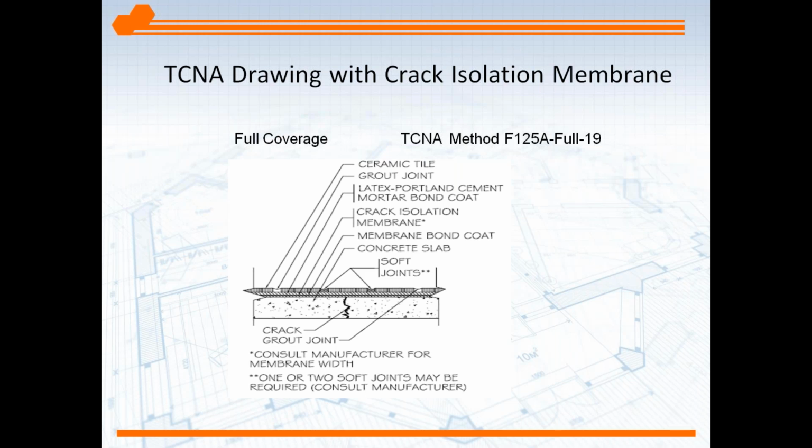You'll also see lots of drawings in TCNA where there's not a membrane included, but if you look in the body of the wording of the drawing, there's a lot of paragraphs that come after the drawing. We're going to talk about that. You'll see membrane options. So you don't necessarily have to call out a drawing with a membrane. You can call out a drawing that fits your situation better and then add the membrane to it.